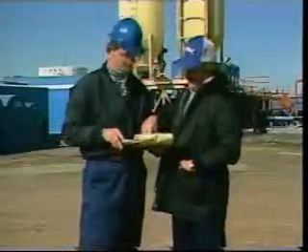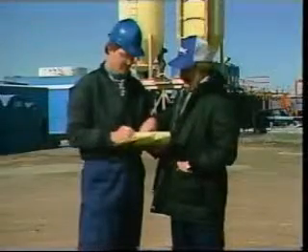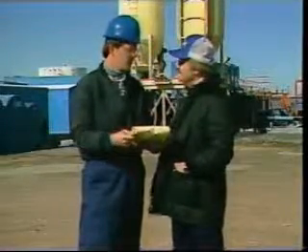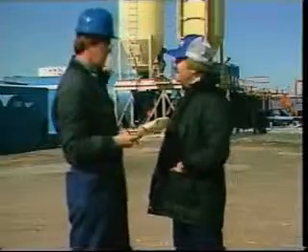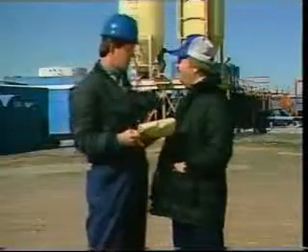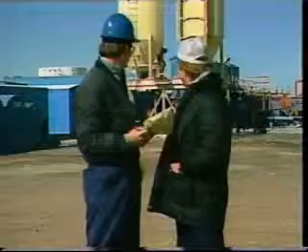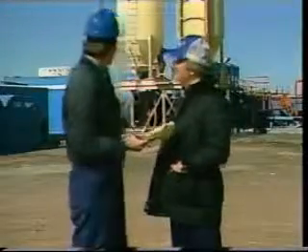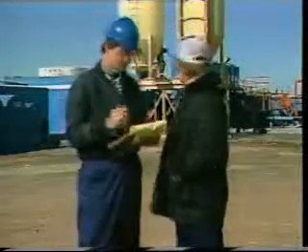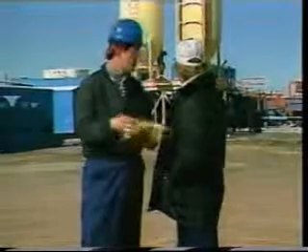Dilution is often used as a means of correcting mud property problems, but this method does not remove the solids, it only decreases their concentration. This technique is also expensive, since large-scale dilution leads to the need for storage of more mud or the discarding of usable mud as space limitations require. In many areas, the safe disposal of drilling mud is an expensive venture in itself.